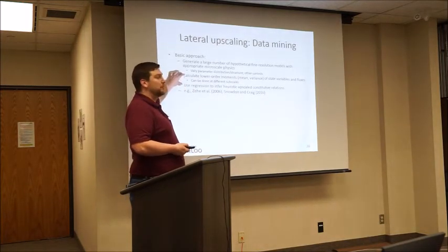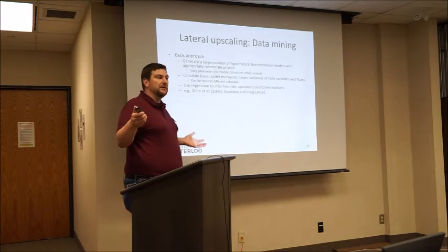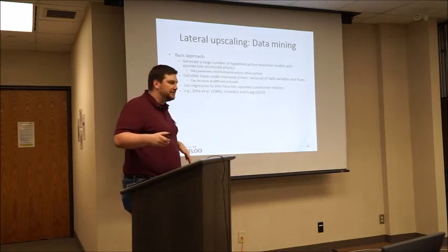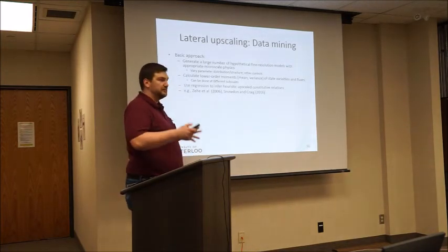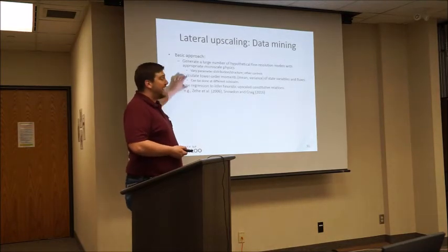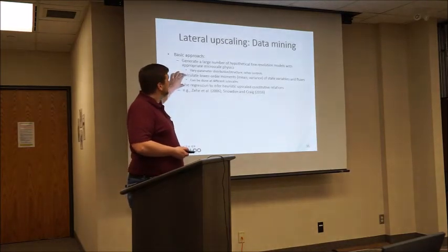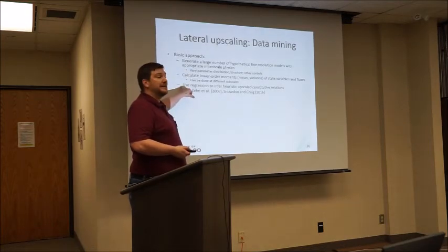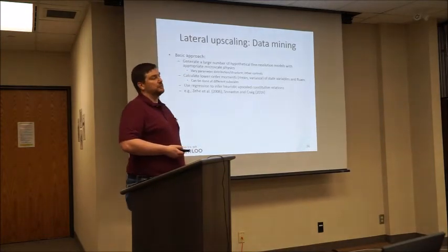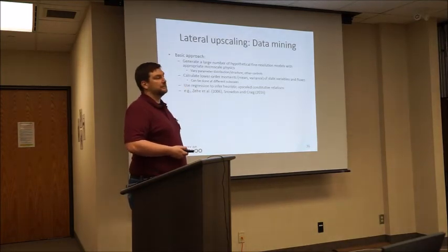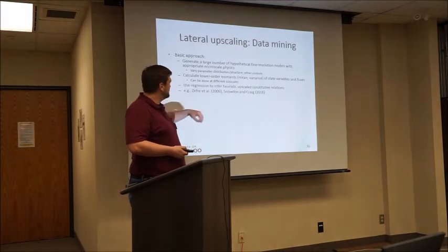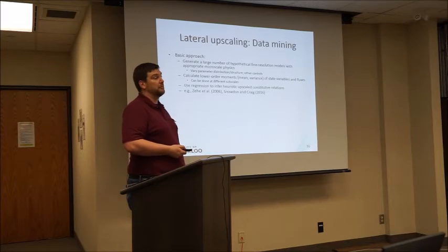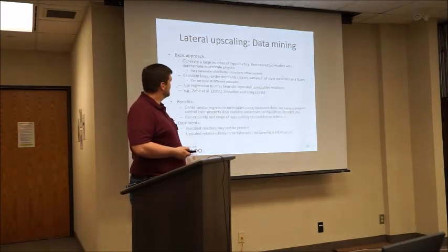So we can take those models, run them under a variety of conditions, a variety of topographies, a variety of soil heterogeneity, focusing in on one of these things, and we can calculate those mean low order moments of state variables and fluxes and try to infer the constitutive relationships through regression. And so this was used for unsaturated flow in the past and also for lateral groundwater flow, base flow from systems, and I'll be talking about that.